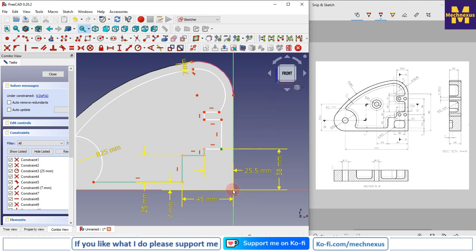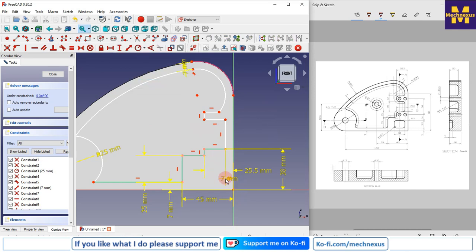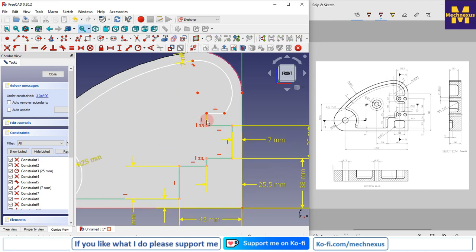So I will select this point and this point, give horizontal dimension of 7 mm. Now we will constrain this line, which is 25. While constraining, start from one end and go constraining one by one. You will not feel any problem in constraining. So this and this point should be vertical, so I gave the vertical constraint, and this is the 13,